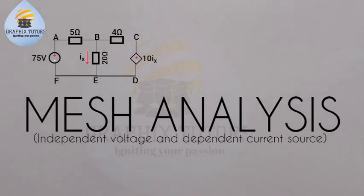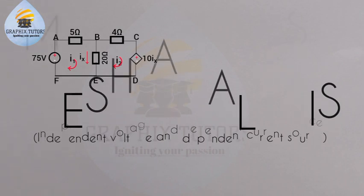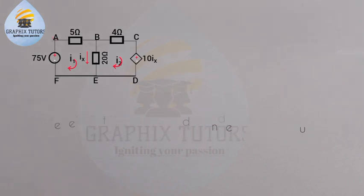Now in the first mesh, let's call the current I1. The second mesh we'll call I2, and we assume both of them are flowing in a clockwise direction. So because this is mesh 1 having I1, the current flowing in this part here will be I1, and this is I2, the current flowing in this part here will be I2.